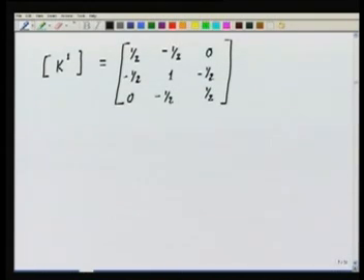So one thing you should see is that if I add all the terms in a row or all the terms in a column of the stiffness matrix, I get 0, which tells me that the stiffness matrix is actually singular. Okay, it should be, because if I look at an element as the whole domain, then obviously the element should give me a singular stiffness matrix, because the global rigid modes are not constrained. What are the global rigid modes? That corresponds to the constant u. Okay, so we have to fix one value of u. In fact, the rank deficiency of this matrix is 1. Okay, this one can be checked.